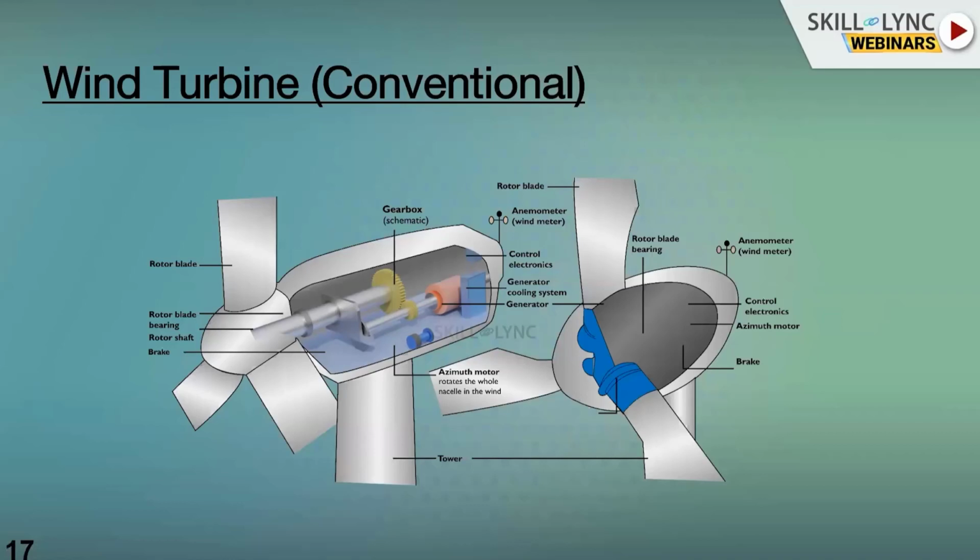Depends upon the capacity, the gearbox, generator, and blade hub will vary. So this is the conventional one. The anemometer will give the signal to the system. Then only the blade and hub will rotate. While the hub is rotating, the main shaft will rotate. The main shaft rotating will connect to the pinion, which rotates the generator. This is the normal technology available right from the beginning.